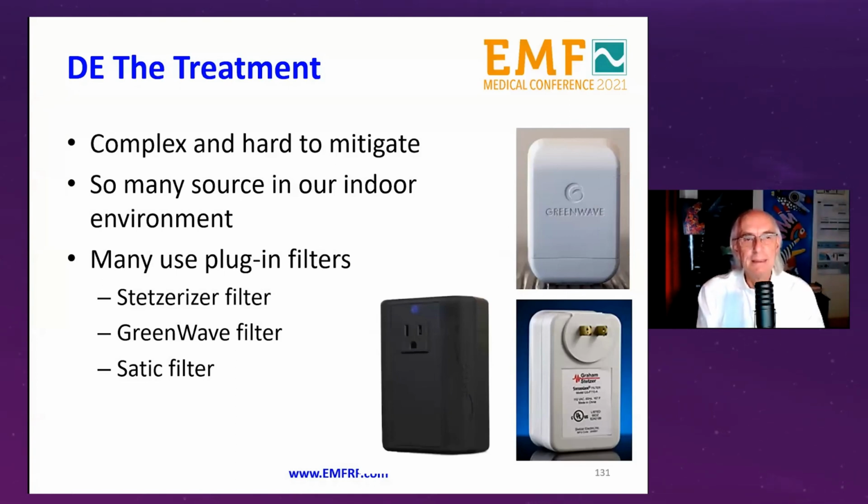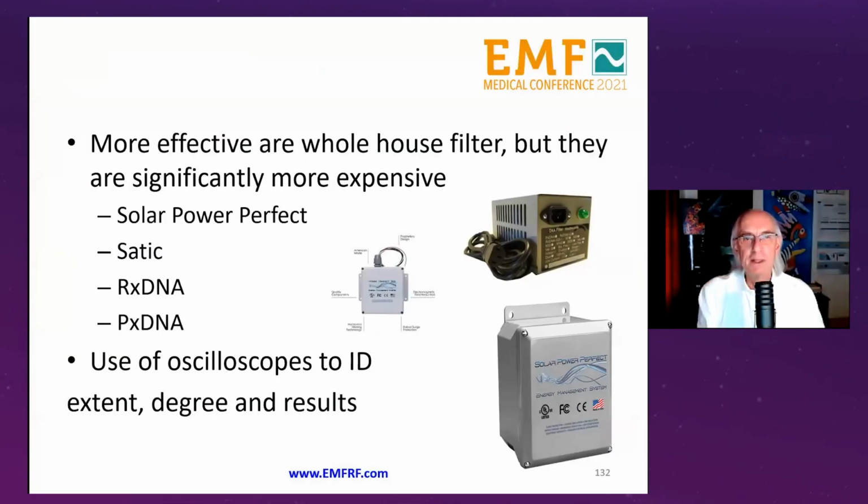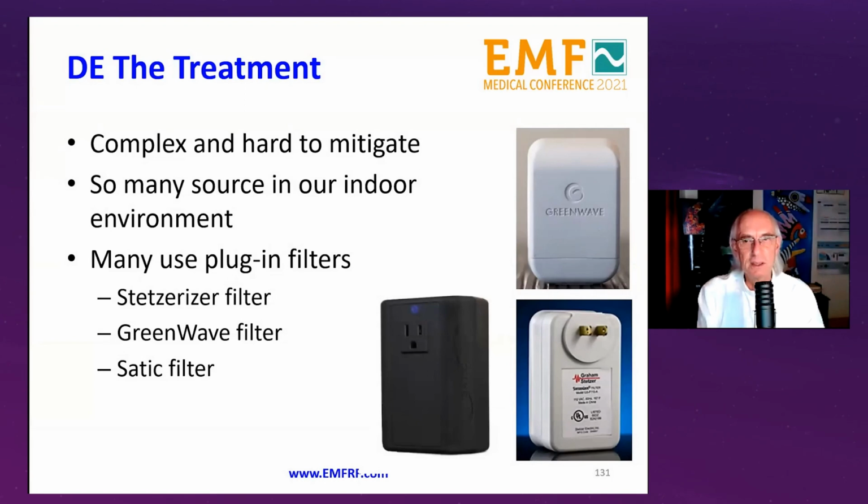What's the treatment? Well, there are a lot of plug-in filters which are being sold all over the place. So you actually plug it into your electrical outlet, and then supposedly it dissipates. A lot of people feel better afterwards. A lot of scientists say, well, we don't really know if this is the right way to go. One can show that these frequencies move somewhere else. However, we need to understand that this is not the best solution, because they actually use electrical power and they also heat up. And if you have wiring errors inside the house, then they can create large magnetic fields and they can create fire hazards. So you want to make sure that you don't have any wiring errors before you plug these things in.